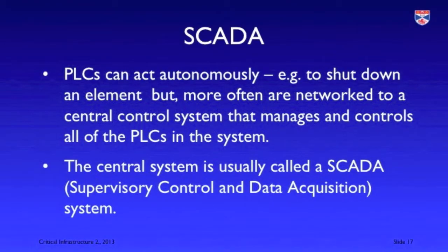PLCs can be designed to act autonomously so that they have no connection with any other system, but more often they are connected to a central control system, and this is called a SCADA system. SCADA, standing for Supervisory Control and Data Acquisition System. SCADA systems are used to monitor, coordinate, and issue instructions to individual controllers within the infrastructure. I'm going to be talking about these in more detail in my next video.